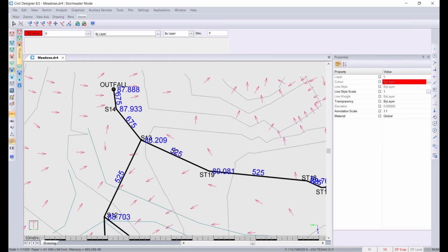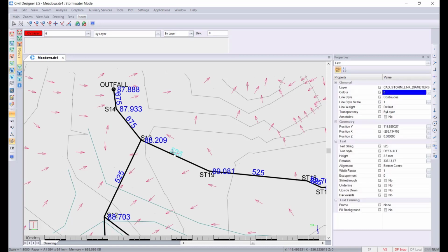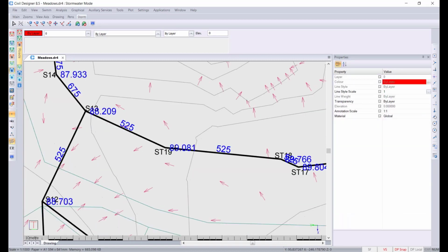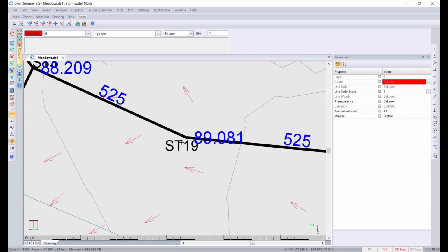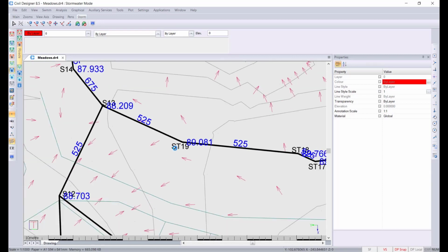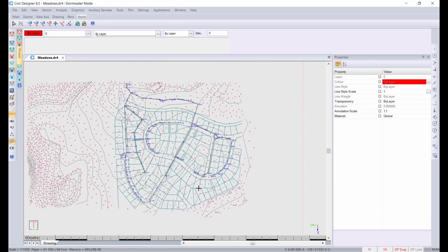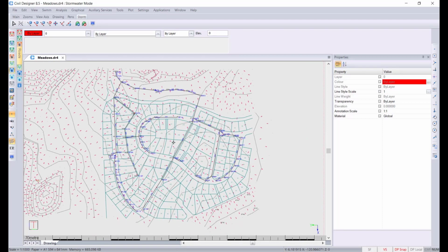They don't have to be this. You can also have millimeters and a diameter sign in front. It will also still capture the text, as long as it is text and sitting in its own layer close to the center of the pipe, and the invert and names need to be close enough to the terminating point where the node will be placed for the node information. We have this network that we'll convert now.